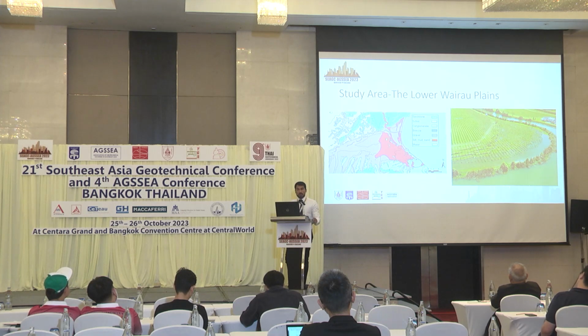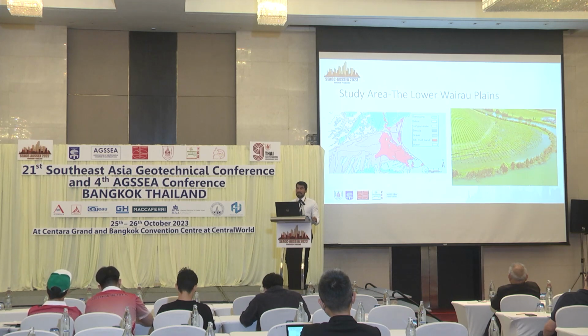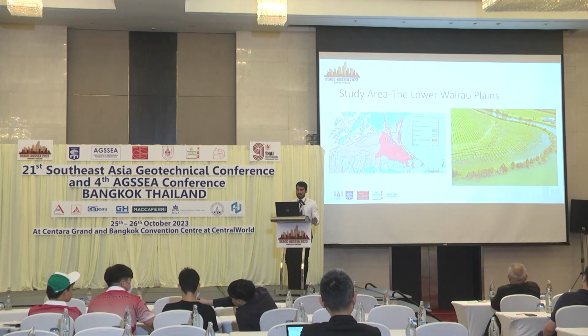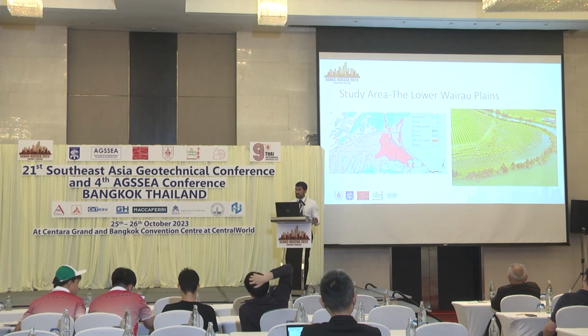And also the groundwater model has shown that the groundwater depth is shallow, approximately 2 meters in most of the region. The other thing is that in the 2016 Kaikoura earthquake, liquefaction was also observed in some regions in this Marlborough district, for example, Blenheim. That's why we took up this project to do the mapping of the whole region and then do some site-specific analysis to see, at the sites where gravel is dominant, how the soils will behave, and it can help in future developments and future projects.